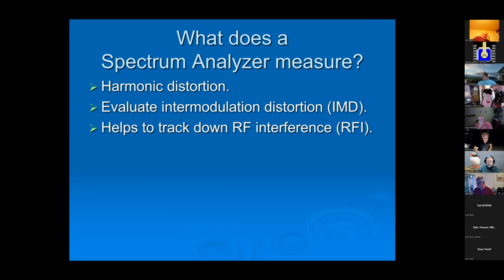So with a portable hand spectrum analyzer that's battery operated that you can carry around with your hand, you can put a little antenna on the thing, and you can go around to, like, let's say you got some noise that's just wiping out 20 meters.